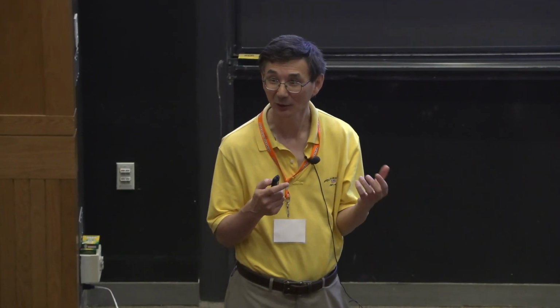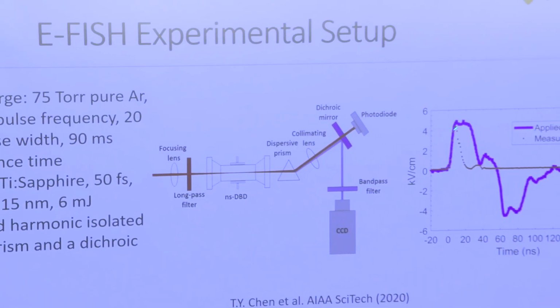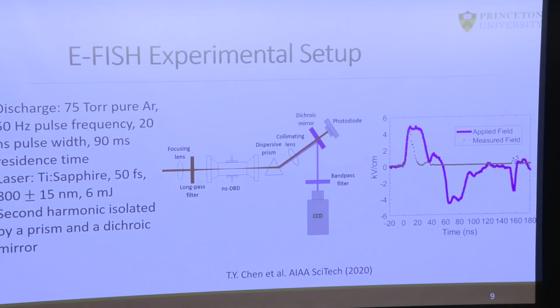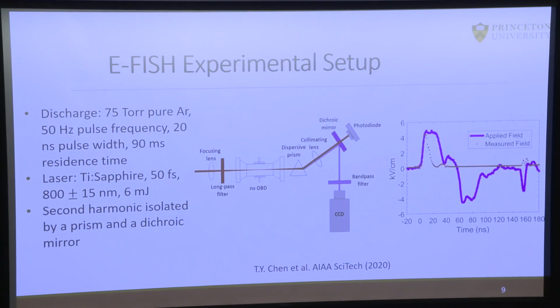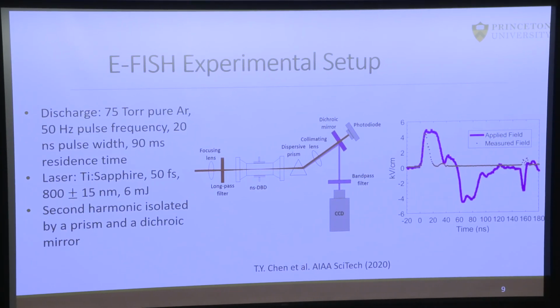Before breakdown, you don't have enough electrons and ions, so the electric field is there. After you break down, you generate a lot of electrons and ions, and then the electrons and ions quickly move and shield the effect of the electric field. So the electric field now only exists near the cathode and anode. There's no electric field between them after breakdown.